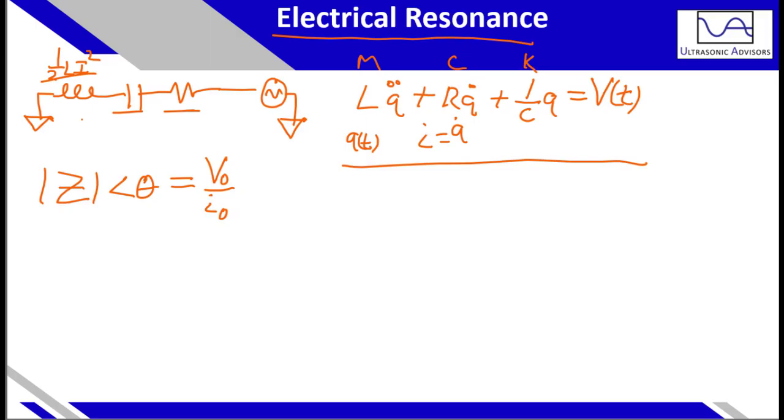Now this is slightly different than the relationships we derived earlier for the mechanical system, because we typically think of voltage as an input. Now your input's on top. Admittance, which is another electrical parameter, describes current as being an output. But typically the analysis is done with impedance, and it provides exactly the same information. So we'll continue to use that for our analysis.